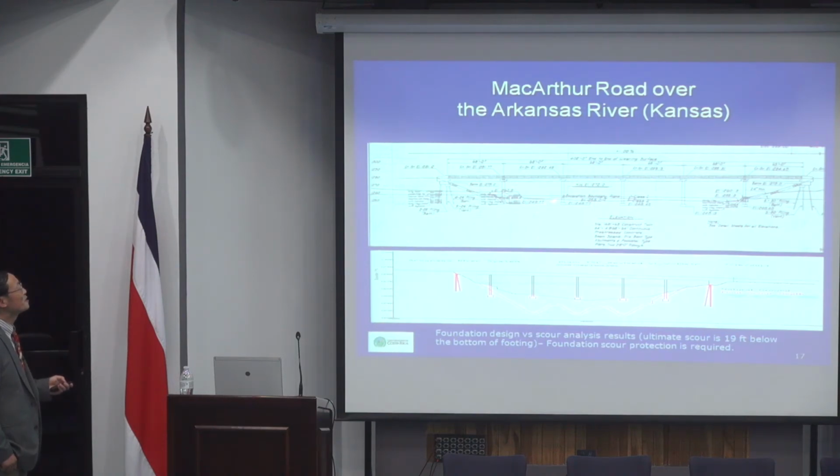When the bridge was built, actually they had sufficient depth, I think more than a meter of soil. Now the inspector found there's actually not much soil left. There are big cavities here already. Then they did a scour analysis, and this is a calculated scour, which means if you don't do anything, all the soil could be washed out and the bridge may collapse.